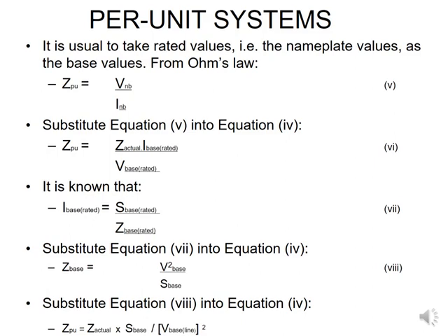Remember, it's the same throughout your system once you've been given or determined it, divided by my V base line squared. So you must remember it's a line to line voltage and you need to square it, okay? And you must remember also that that voltage changes on your system according to which side of the transformer you are at and what that voltage on that side of the transformer says you must utilize.